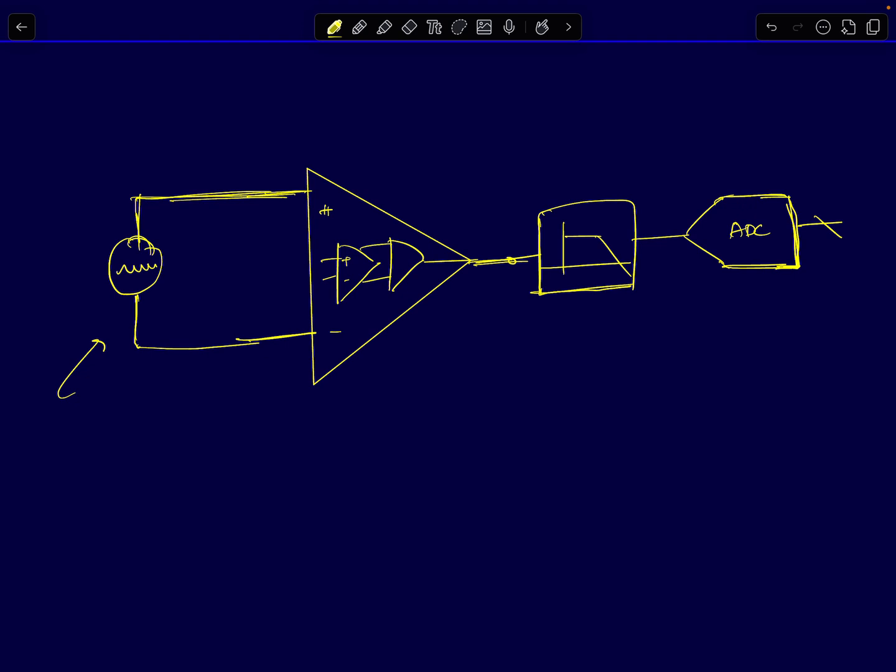In some specific applications, medical especially, medical imaging and some interesting applications, the resolution of the ADCs can be very high. When you talk about ADCs, the defining characteristic of an ADC is what we call the effective number of bits. I mean, I can have an ADC which is 20 bits, but if I measure its SNR, signal to noise ratio, it will not correspond to 20 bits. So what do I mean by that?